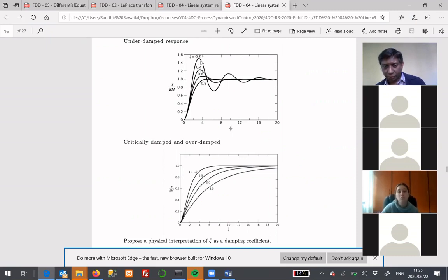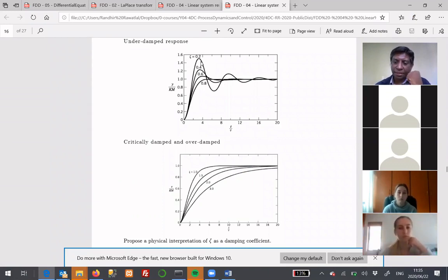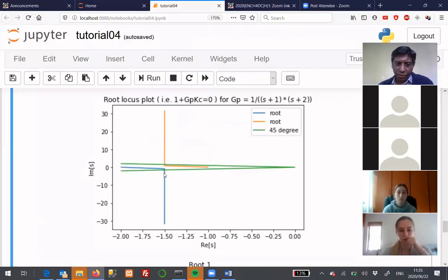And that first overshoot is basically giving us the maximum amplitude. Where you have that maximum amplitude, you can estimate your amplitude ratio, and that lets you constrain yourself. So you can say, I can see Kp is 0, 1, 2, 3, 4, 5. Okay, so Kp is 5 here.